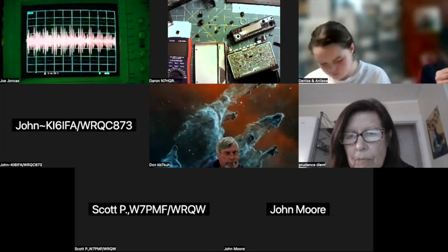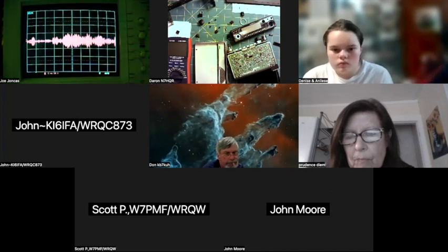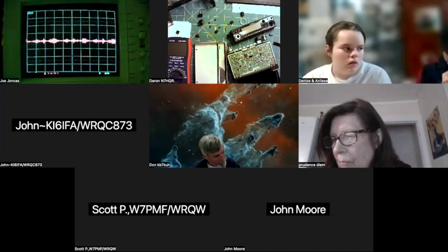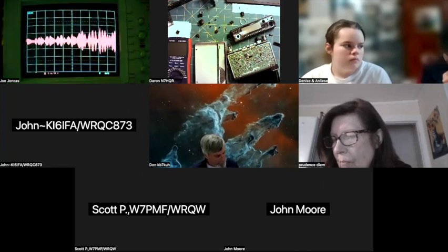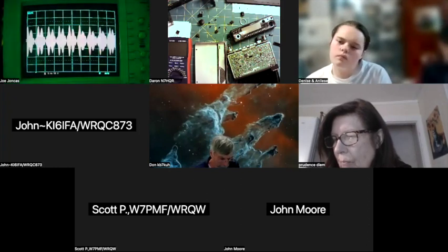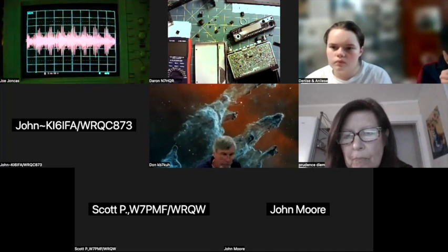Now, do you remember me talking about RMS? Yeah. We multiply the peak by 0.707. So what we do here is we take this peak, which we can see real easy on the oscilloscope. And that's how I do it every time I measure.